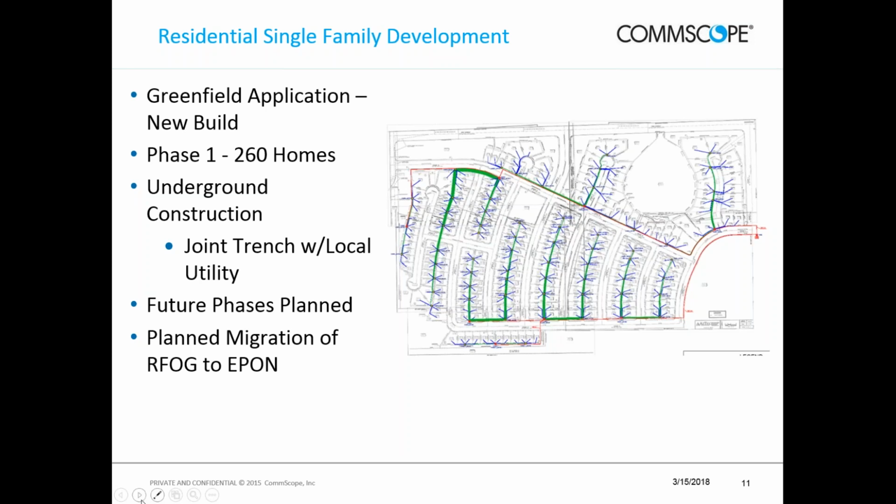And then, as I mentioned before, a lot of these are designed and built in phases. So the complete thing won't be built at once, but when you do the design for it, you need to plan ahead with regard to your feeding fiber coming into the project, that it's going to have enough fibers to serve the whole area. So you must think quite a ways ahead when you're dealing with planned phase development of these greenfield fiber to the home builds.